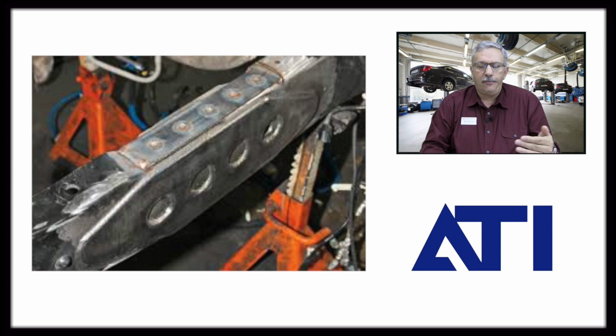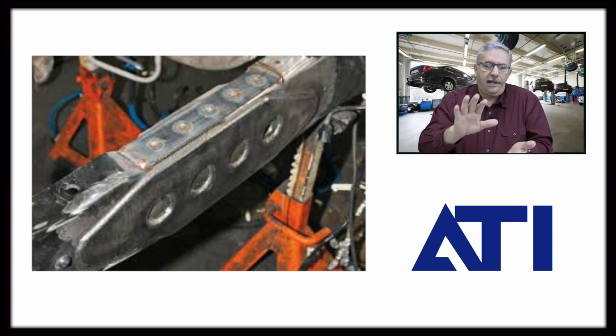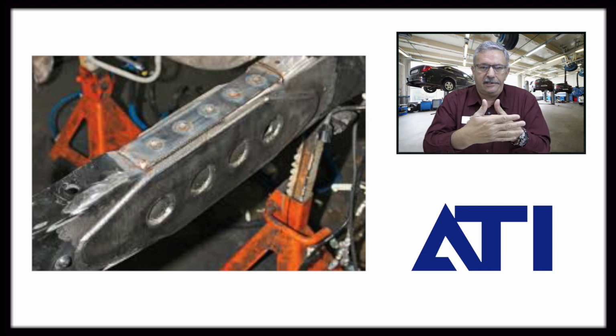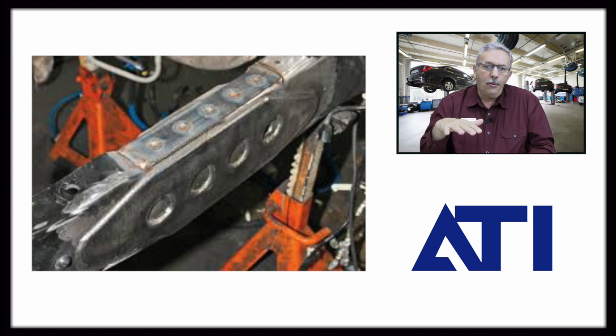One can be done with what they used to call fish plating. I could put a continuous weld on it and put plates on both sides of the weld, and that was perfectly fine for a mild steel frame repair. Now with the hydroforming, we enter into a lower strength, high strength steel.